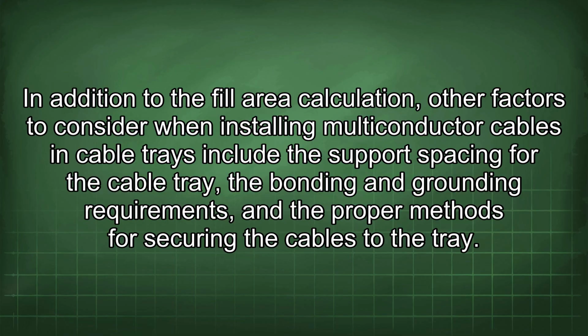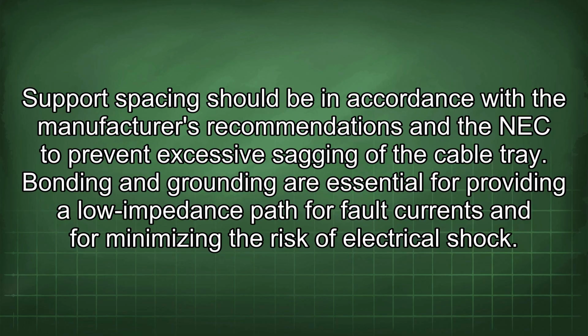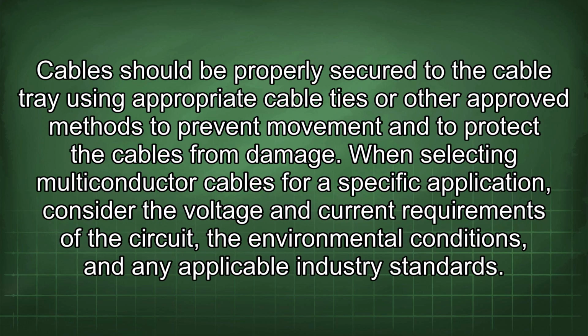Support spacing should be in accordance with the manufacturer's recommendations and the NEC to prevent excessive sagging of the cable tray. Bonding and grounding are essential for providing a low impedance path for fault currents and for minimizing the risk of electrical shock. Cables should be properly secured to the cable tray using appropriate cable ties or other approved methods to prevent movement and to protect the cables from damage.